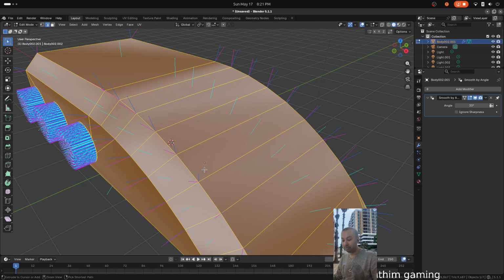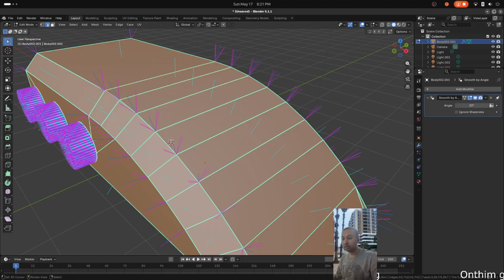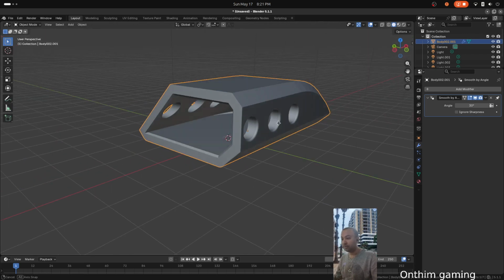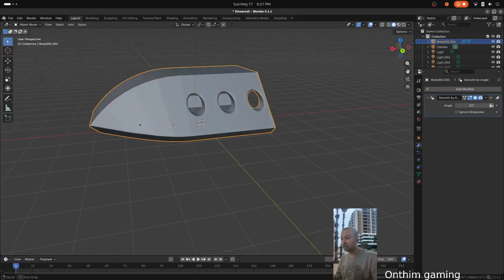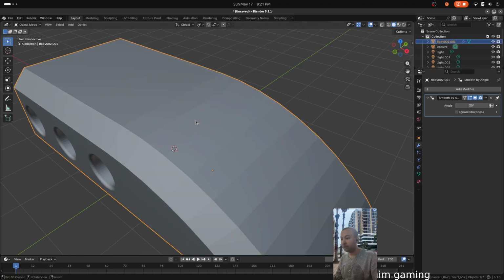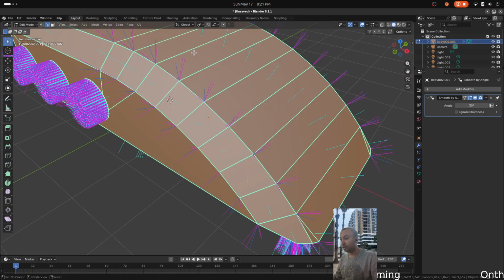And you can see before and after here. Before you don't have it, and after, let's do it again. Normals and split. Now each segment can maintain its own property without affecting its nearby faces. Now you see the result has been improved significantly, but we can still see the limited geometry because it's not being interpolated here.